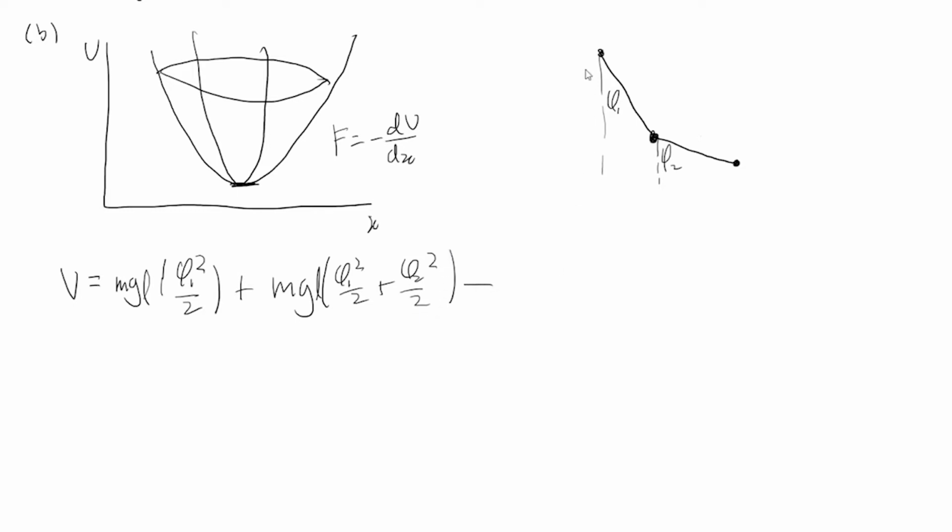And now we have to do the potential energy due to the centrifugal force. So the net work done, in general, at a radius r, since the force is m omega squared r, if we integrate that over r, we get m omega squared r squared over 2. And the potential energy is going to be negative, because that's how it's defined. In other words, things try to achieve lower potential.